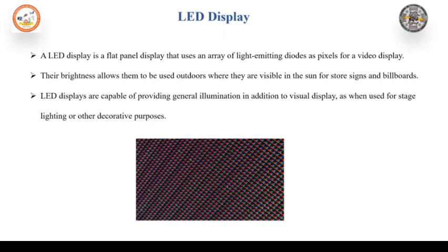The operation of the LED is based on the phenomenon of electroluminescence, which is the emission of light from a semiconductor under the influence of an electrical field. The recombination of charge carriers takes place in a forward biased p-n junction as the electrons cross from the n region and recombine with the holes existing in the p region.